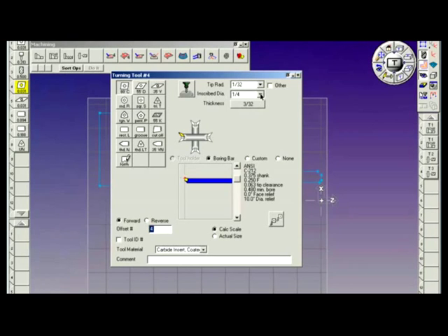If I change my inscribed diameter to 3/8, the boring bar appearance changes in the viewport. It gives me a minimum bore requirement of 770 thousandths, and that's too large for that 1/2 inch hole that we've already drilled in the part. So by controlling the inscribed diameter, I see the correct information here. I've got a minimum bore requirement of 480 thousandths, so that'll work just fine.